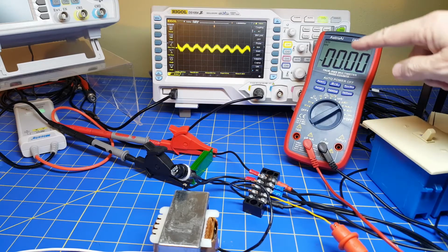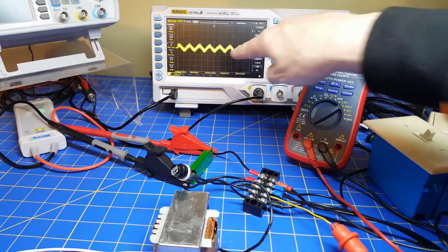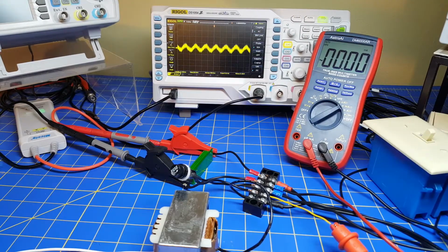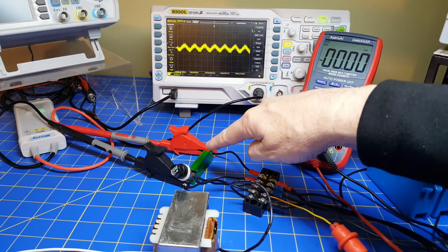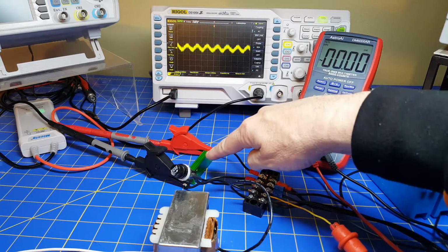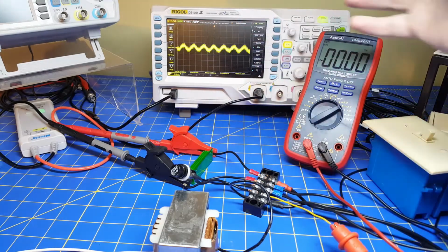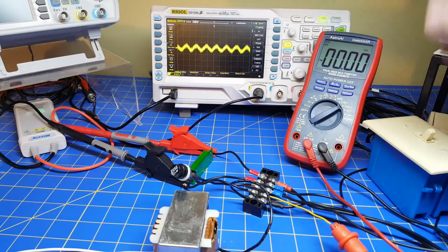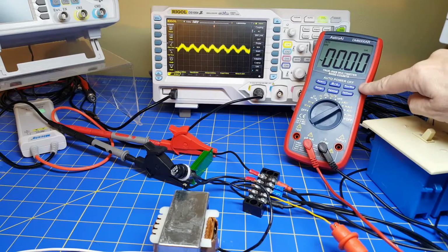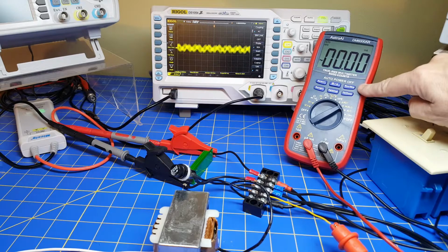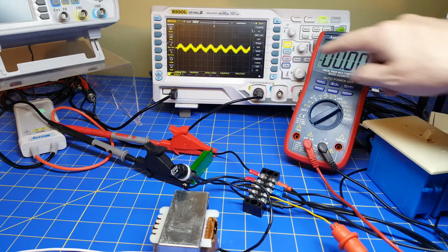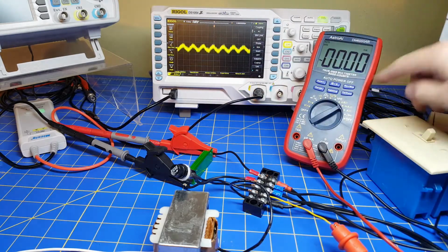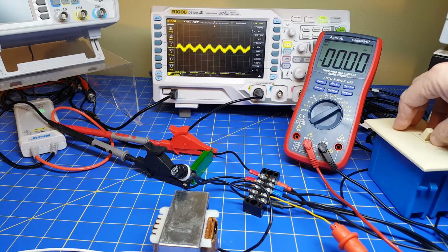So what I'm going to do is turn this on and measure both on the scope and on the meter. Now the scope has 50 millivolts per division, and since this is 0.5 ohms, we should expect the value of current to be twice what we see here. Again, it's kind of noisy, and that's why it's nice to have the multimeter, because it hopefully will clean up the reading and give us a more direct value. You can see with the noise here, there's 0 coming through the multimeter, so this is just noise. So it should help us get a more accurate reading.